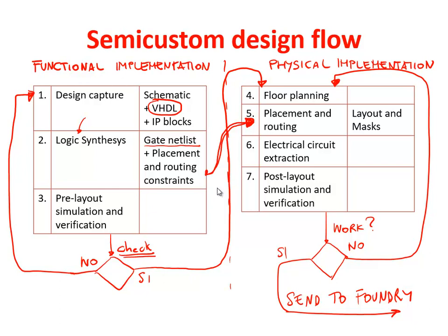For example, provide some input stimulus and verify if the outputs are what I expect, and then check if the operation is correct. This is what is called a pre-layout simulation and verification. It's called pre-layout because I do not have a physical layout. I'm doing it on a logical circuit, on a circuit at the gate level.